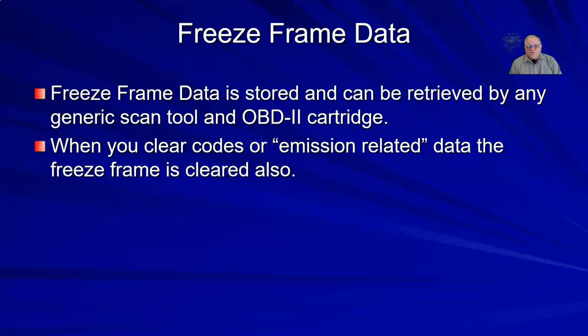When you go to clear codes, it will clear your freeze frame data. So if you think you will need that freeze frame data, make sure you get that before you clear the codes or clear the emission related data.